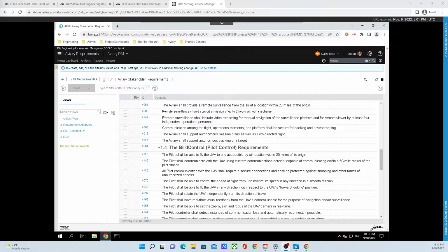We are now on Task 3 in the Getting Started with IBM Engineering Requirements Management DOORS Next Quick Start. Task 3 is about creating a change set and modifying the stakeholder requirement. In this task, you will first examine the traceability from the stakeholder requirements to the system requirements that satisfy them downstream. You will then create a change set such that you can start editing the requirements to enact the requested change. Lastly, you will edit the stakeholder requirement to begin enacting the change.